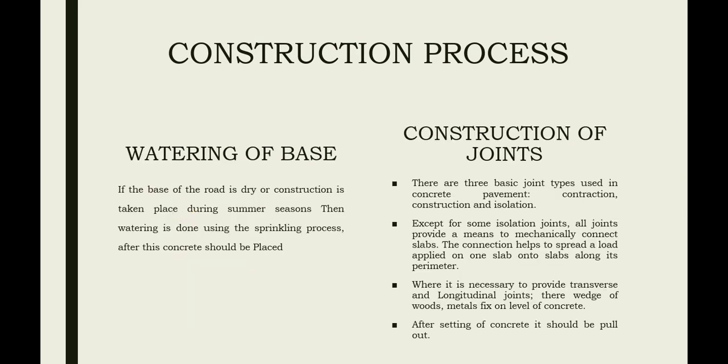Next is watering of base. If the base of the road is dry or construction is taking place during the summer seasons, then watering is done using the sprinkling process. After this, concrete should be placed.